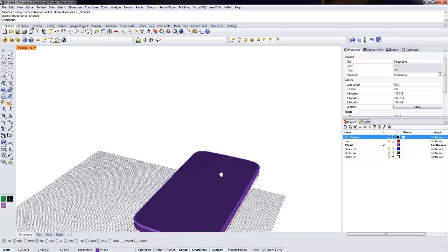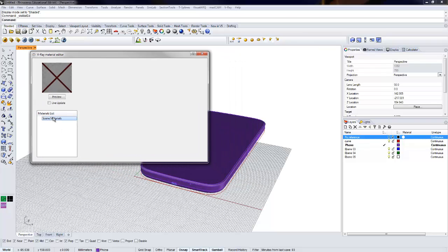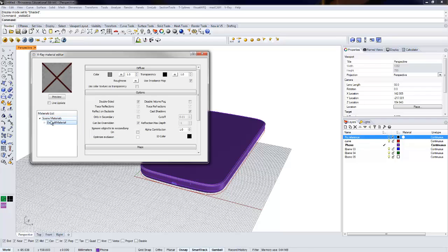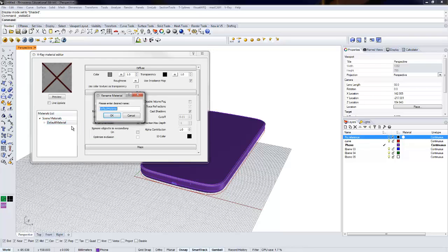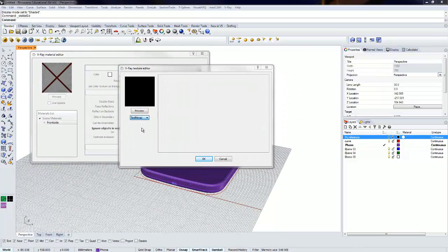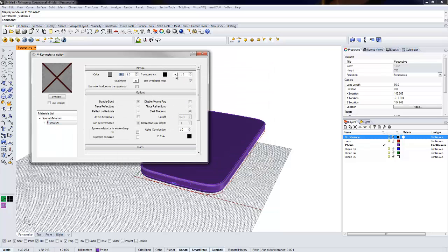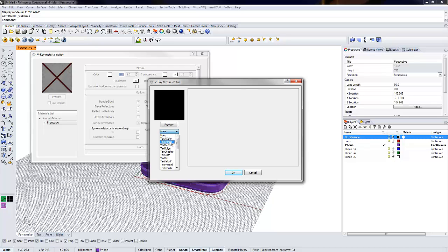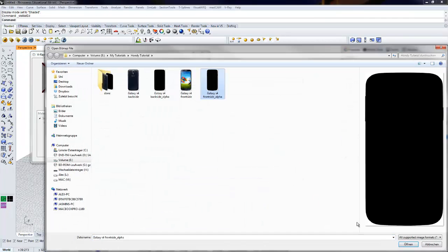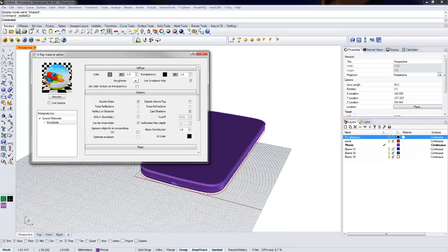So the next thing is we're going to do the materials. So open the material, create a new standard material, and we're going to name it front side. We're going to put in the diffuse. We're going to take a bitmap and take the front side. Okay, that's good. And now we're going to use a transparency map. It also works like with the bitmap, just take the bitmap and take the frontside alpha. And to test it, press preview and you see, okay, you got the picture there.